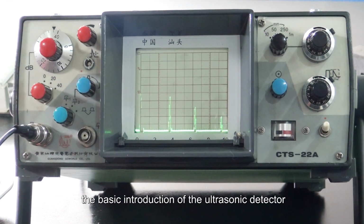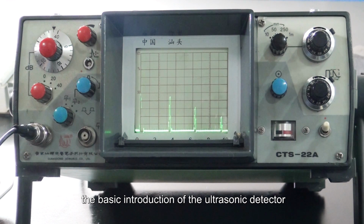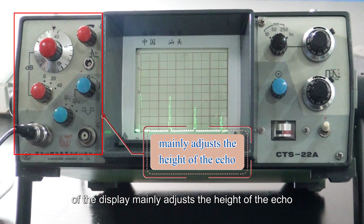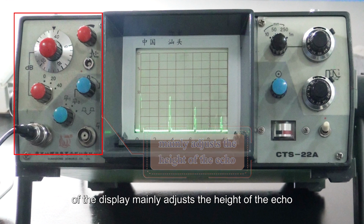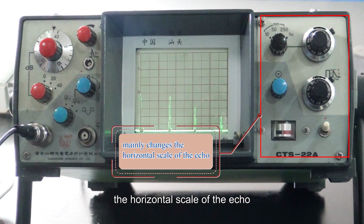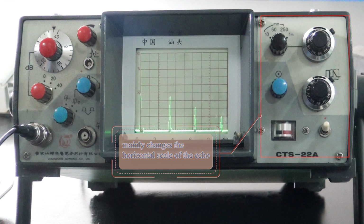Well, the basic introduction of the ultrasonic detector has been completed. You should remember that the knob on the left of the display mainly adjusts the height of the echo, while the knob on the right mainly changes the horizontal scale of the echo.